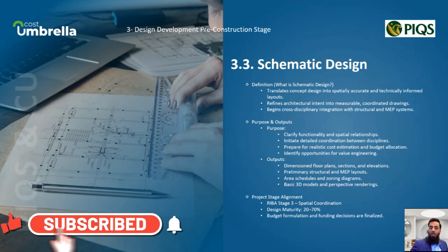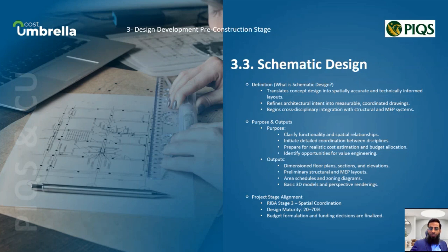Let's say someone proposes a glass curtain wall and open plan spaces, but the cost exceeds the budget. The value engineering team may suggest combining glass with cheaper composite cladding and optimizing the layout for natural ventilation to lower HVAC cost. The result will be a revised design, integrating value engineering ideas, reducing cost while preserving the vision and gaining client approval.